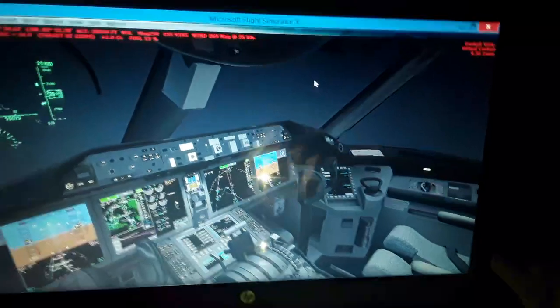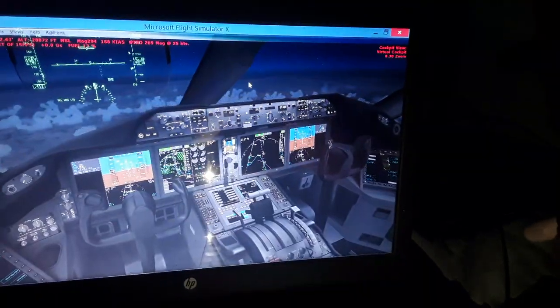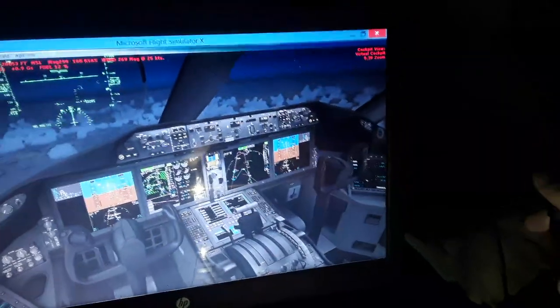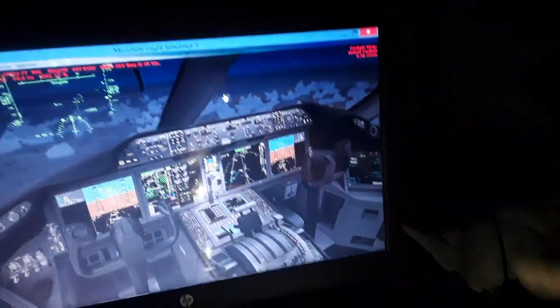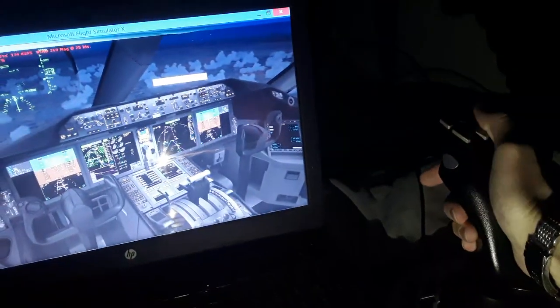So we're gonna stay with this view. We need to initiate the descent. We have 7 more minutes. So retract all the flaps. Thrust maybe more idle and pitch down the aircraft for descent. We keep flying manually over here.